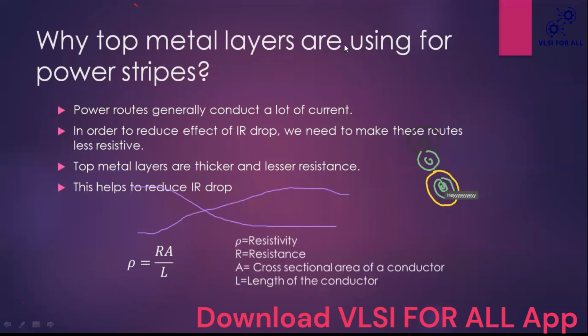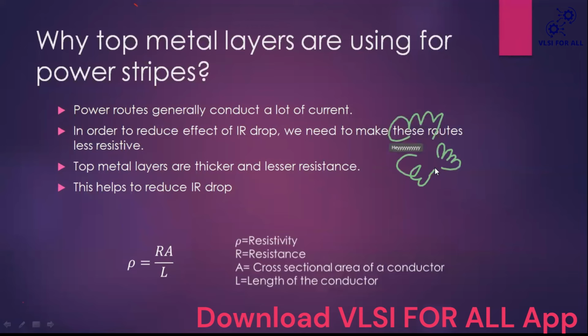See guys, why are top metal layers used for power stripes? I think you people know. We do power planning in the top metal layers only. If my design has 10 layers, then I use 9 and 10.